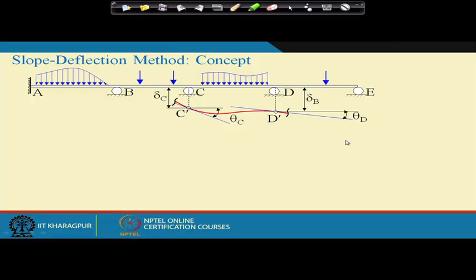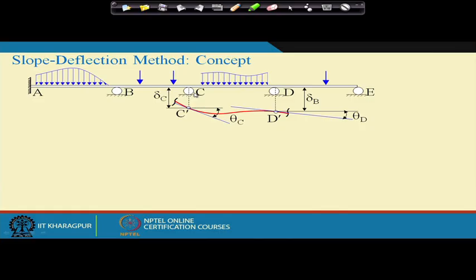Okay. Now if you remember the last class when we discussed the concept behind displacement based method, since the displacements are unknown here, in the primary structure we need to remove those degrees of freedom, right. We need to make the structure kinematically determinate, each segment of this structure. When you do that, the first step gives the primary structure in which all the joints which are roller supports here become fixed joints. Then we took each segment separately.